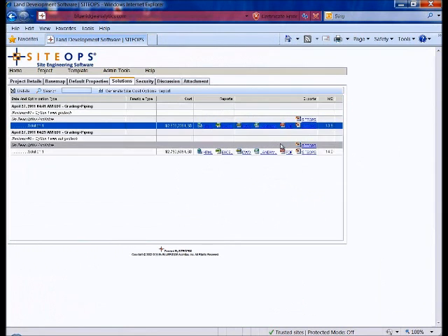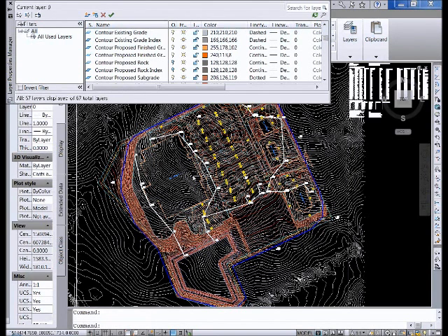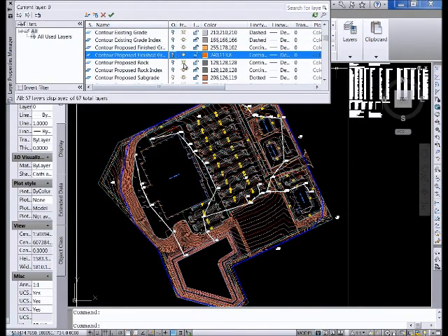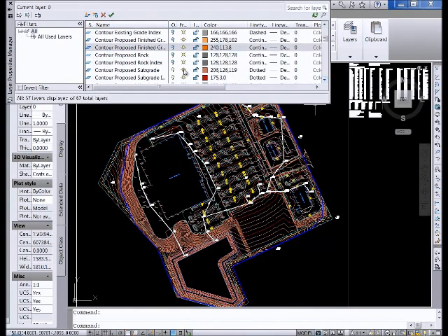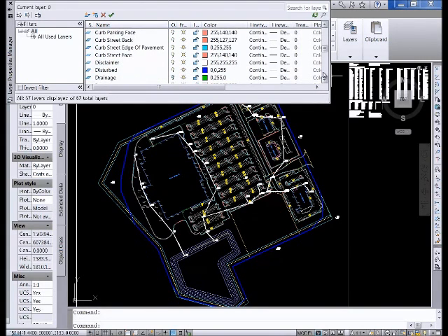Now we also bring this in for an output as an Excel, but you also have DWG and LandXML files that you would take for the design you want to go forward with in the construction document phase. For example, pick the DWG and open it up inside of Civil 3D. We'll turn off a few layers. Now we give you finished grade and finished subgrade contours, because we do grade the subgrade, since you can put those material thicknesses in there. We also give you 3-line curb sections. We give you all the information you need to pick this up and go forward in your design.